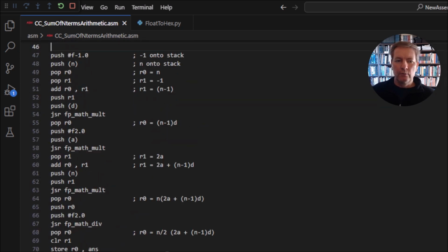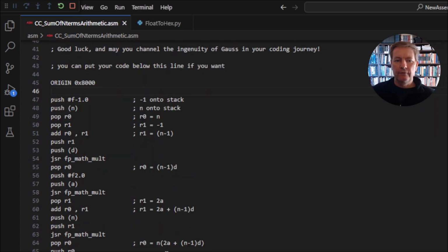So that's my little piece of code, and it's the first time I've gone in and used the push and pop completely within the code. Now the nice thing about doing it like this is that I don't have to bother about saving intermediate values in registers, or saving intermediate values in memory locations and then getting them again.